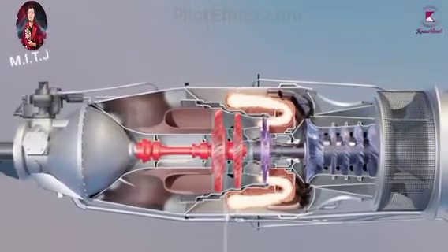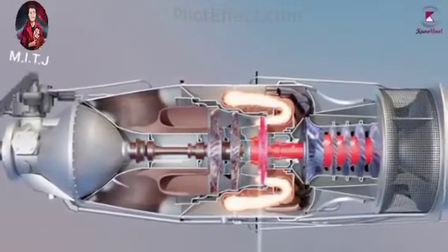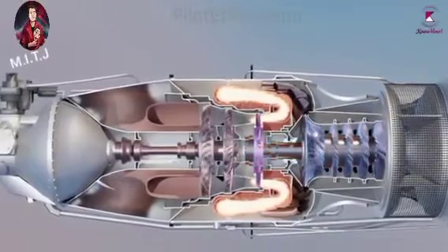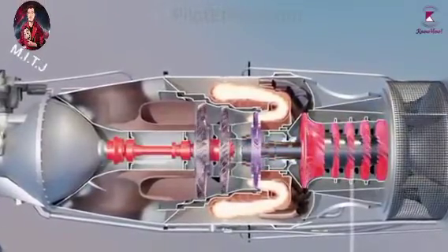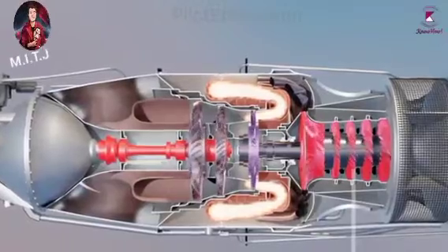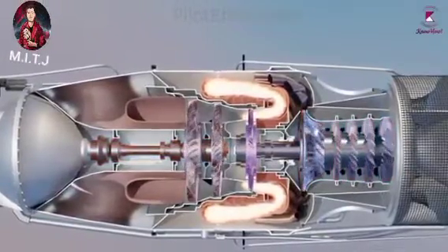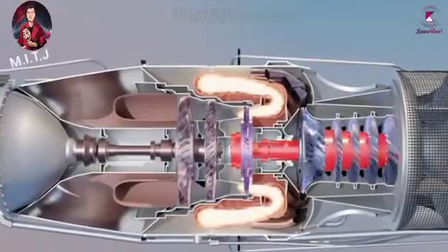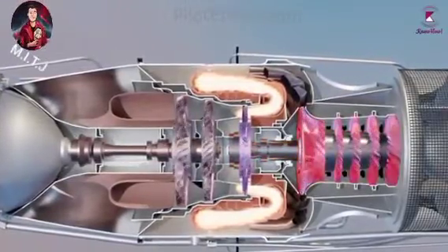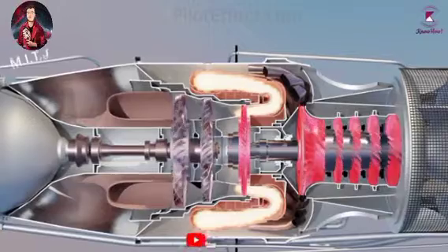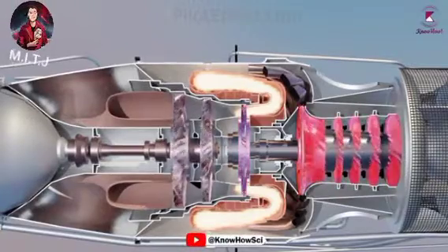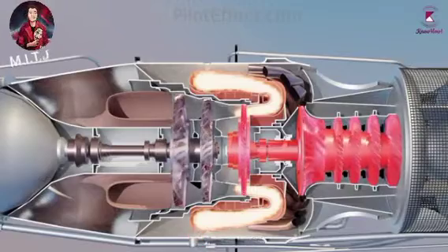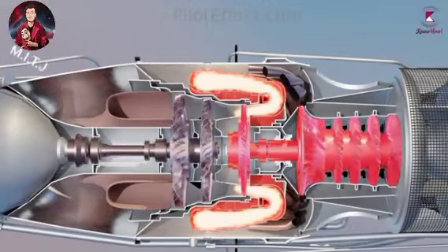The exhaust velocity of a turboprop is low and contributes little thrust, because most of the energy of the core exhaust has gone into turning the drive shaft. Because propellers become less efficient as the speed of the aircraft increases, turboprops are used only for low-speed aircraft like cargo planes. High-speed transports usually use high-bypass turbofans because of the high fuel efficiency and high-speed capability of turbofans.